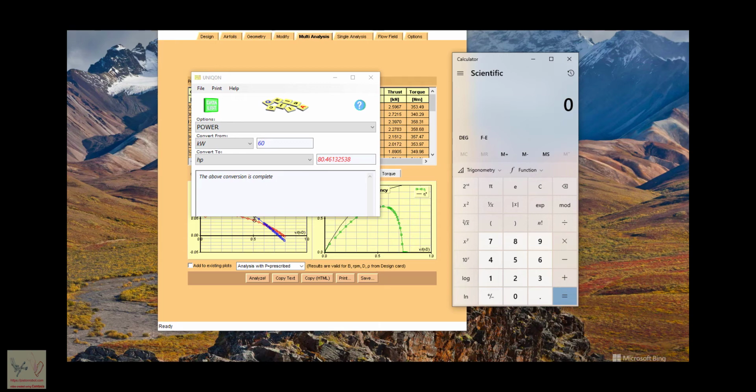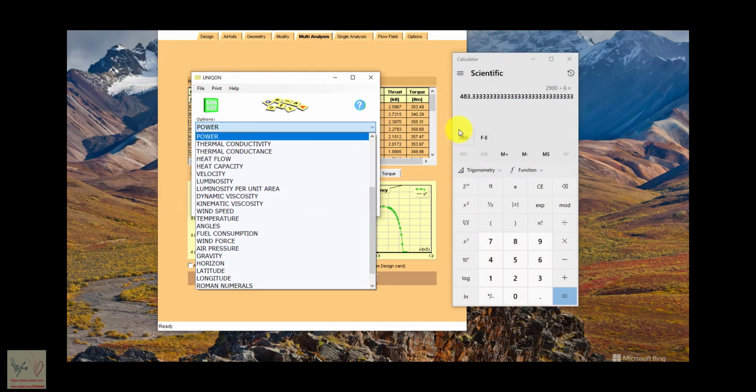We're going to assume that perhaps a 500-pound payload, so that's 2,900 pounds. So if we take 2,900 pounds and divide it by 6 propellers, we have to have 483 pounds of lift on each propeller. And this is the wonderful thing about this program. It prevents you from making all those stupid mistakes that are so irritating.